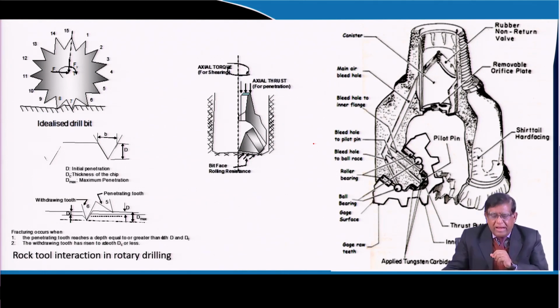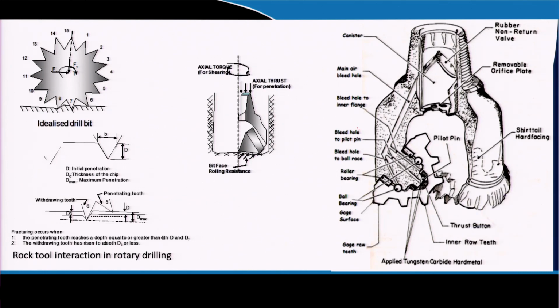In case of rotary drilling, they use a tricone roller bit. If you take a cross section, it is just like a toothed wheel. Now, if it is forced into the rock, you can see that the rock in between gets trapped over here, and when it is rotated, this portion gets chipped off. This is the way it cuts.